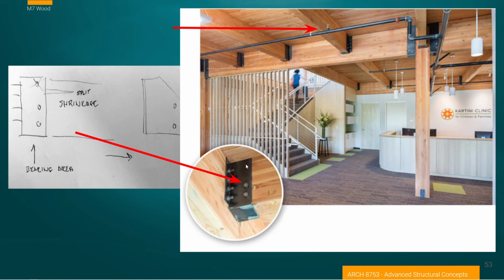And if we were to put a series of holes through all of these at various locations rigidly, through any shrinkage or any changes of the depth of this beam, it would be likely that one of these bolts would cause the kind of stresses that might actually fracture or split this beam. So I'm believing that's why that bolt condition is the way it is.